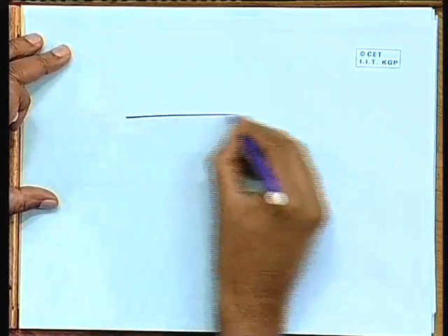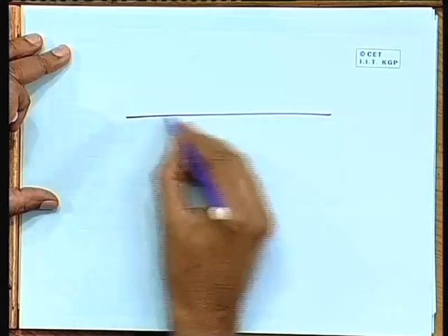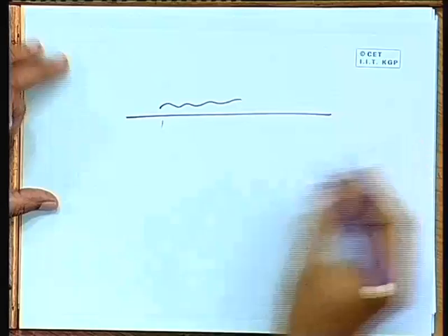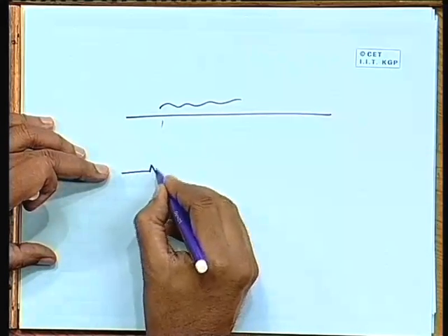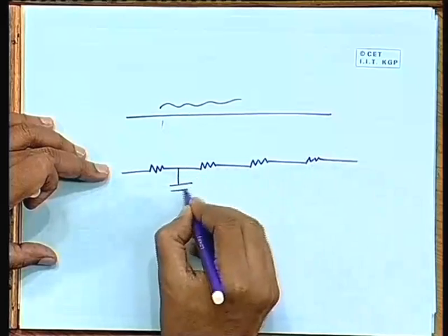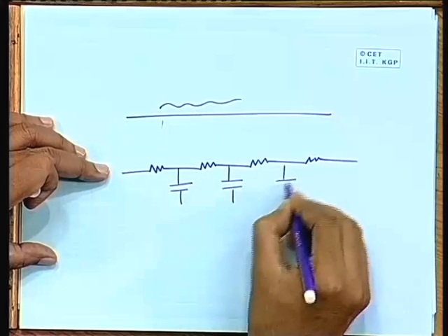Okay, so how will inserting buffers reduce the delay? Simple. Let me briefly talk about it. Say you have a transmission line. On this transmission line, resistive and capacitive delays are all spread out. Now these are often modeled as distributed resistors and capacitors like this.